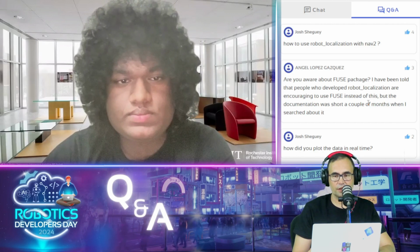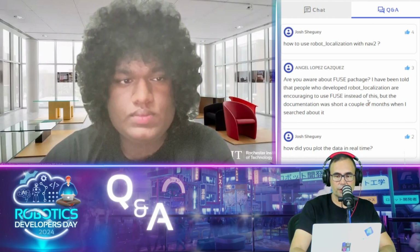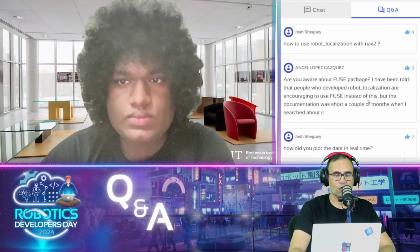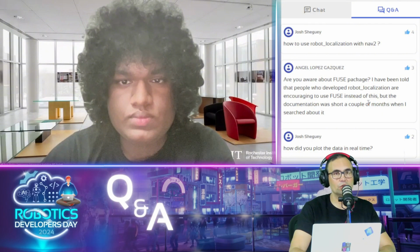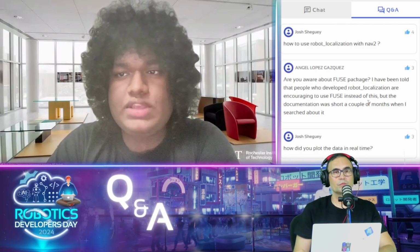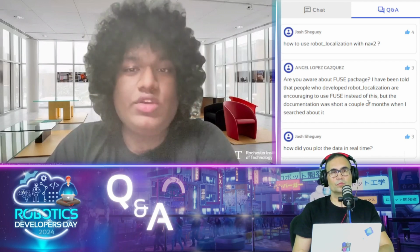Excellent. Then there is one question from Josh Shewe that says, how to use robot localization with navigation too? So how can you combine this? Good question. Remember when I was talking about the map frame? I was saying that it's odom for now, but if you're using AMCL, you can change that. That's where you would modify it.